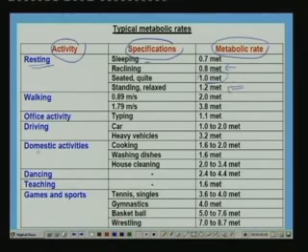You can see that for domestic activities the metabolic rate is quite high. It can vary from about 1.6 to 3.4 met depending upon the specific activity. You can also see that for very strenuous activities such as wrestling or playing basketball, the metabolic rates are very high. It is as high as about 8.7 met in case of wrestling. This kind of data is available in ASHRAE handbooks for more number of activities. So, one can use the handbooks for getting this kind of data.